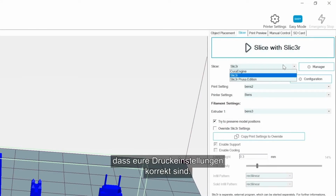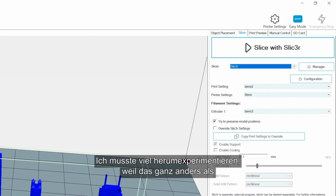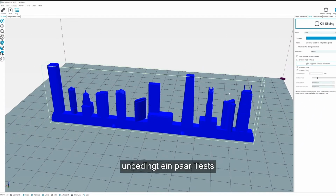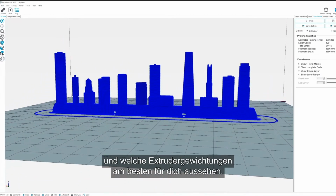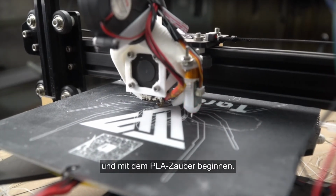Something else that's really important is to make sure you have your print settings correct for the translucent PLA you're going to use. I had to do a lot of experimentation because it was very different from my white or black PLA. So make sure you do some testing beforehand and just figure out what temperatures, what extrusion weight works good for you. Let's now go ahead and get these files sent over and get some PLA rolling.